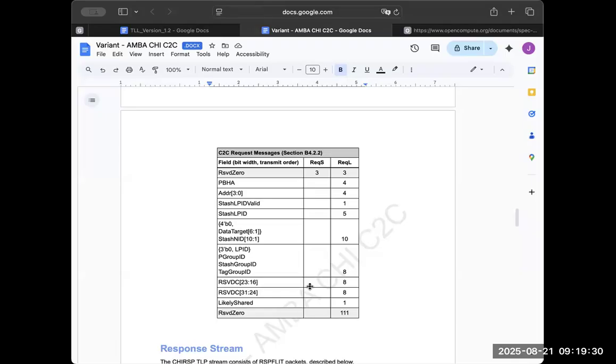And not all of them, like for example, the idle TLP, I don't think it's required for C2C, right? It is, I think, a BOW specific thing to keep the PHY signaling aligned. Right. But the idle TLP is in the main spec. I don't think you have to put it in the variant. No, but that's what I'm saying, maybe we should pull any kind of TLP formats out of there and keep those as variants, right? And then you have the flexibility of whether you use them or not.